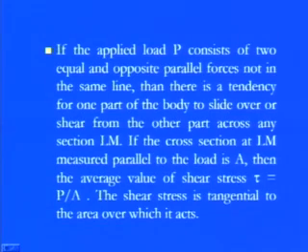This is the meaning of shear stresses, because as we have seen, normal stress components always act perpendicular to the surface of the area concerned. But here, whatever area we are concerned with, on which these stresses or loads are set up, the stresses are always tangential to the area of concern. So we need to be very careful: if we want to find out where the maximum and minimum stresses are, we have to be careful about the area over which these tangential forces or stresses act within those objects.